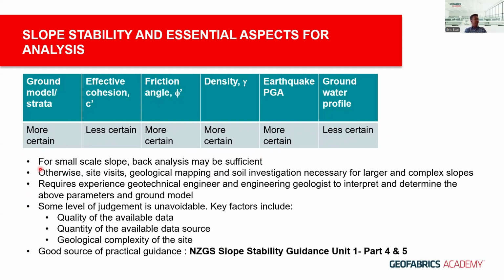But I mentioned here, for some small-scale slopes, most often back analysis of the existing slope profile before failure, and mimicking the failure slip profile, may be sufficient without going through an elaborate investigation.